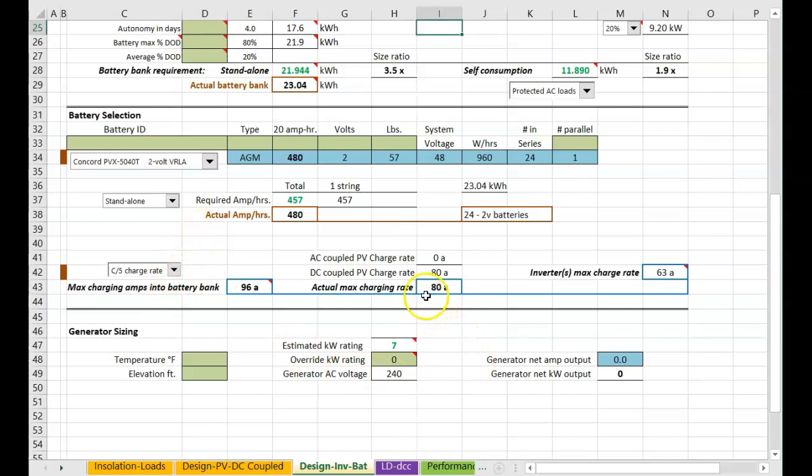And what we take a look at is, what is our charging source? We have 2 charging sources. One is the inverter. If the inverter is calling on a generator or the utility to charge, this is the charge factor based on that particular inverter we have. If we had 2 of them, it'd be twice this much, and we'd be at risk of overcharge. We have 1 charge controller rated at 80 amps, so it's listed right there, and all of those are looking at this. If these are higher than this, you'll get a warning sign over here. It'll say, hey, you're exceeding the capacity of charging this battery. It's possible that you could stress it.